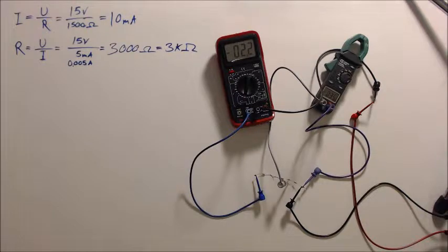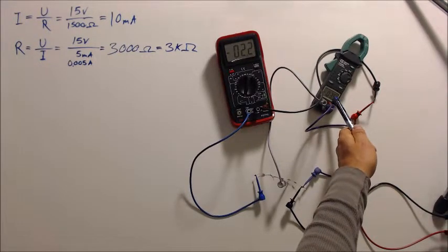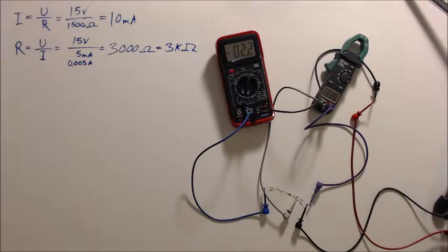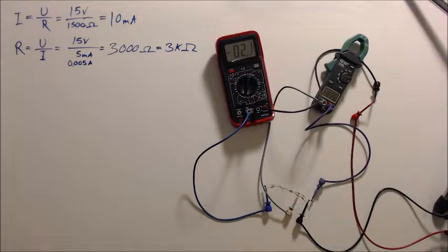Boom. Huh. Even lower. So now we're down to, and our original resistor that we're measuring across is only 3.5 volts. But we know there's 15 volts on this circuit. So interesting. By adding another resistor, a 3.3 kilo ohm resistor, we now have lowered our current even further. But that's not that surprising. We already figured that it was lowered by adding another one. So the more resistance, the lower our amperage draw is.